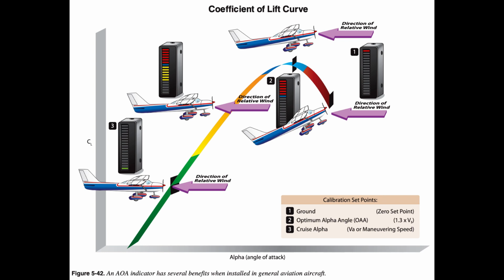This critical AOA does not change with 1. Weight. 2. Bank angle. 3. Temperature. 4. Density altitude. 5. Center of gravity.